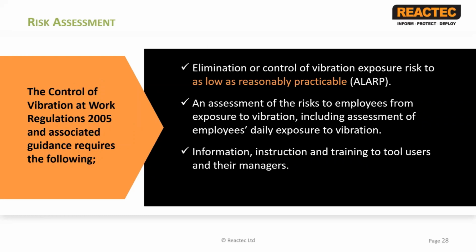The requirement to carry out a risk assessment of exposure to hand-arm vibration comes from the Control of Vibration at Work Regulations 2005. These regulations require that employers should either eliminate or control to as low a level as reasonably practicable exposure to hand-arm vibration.